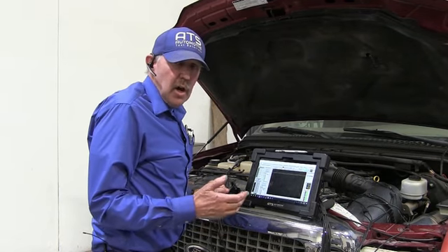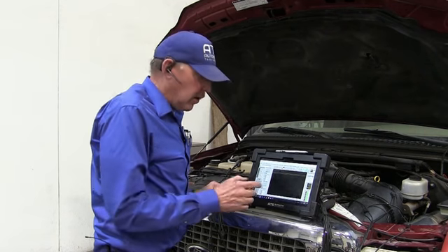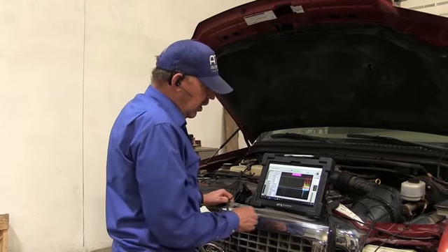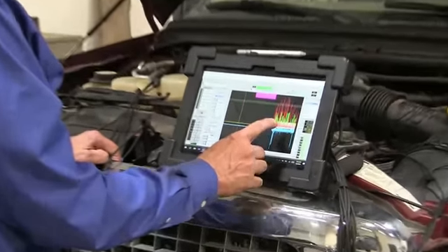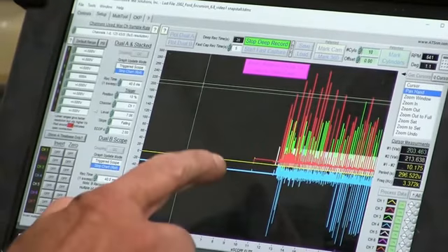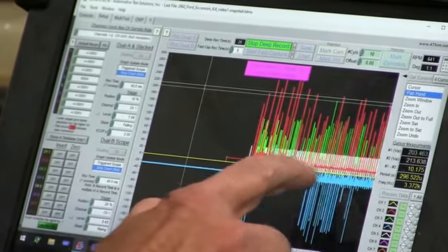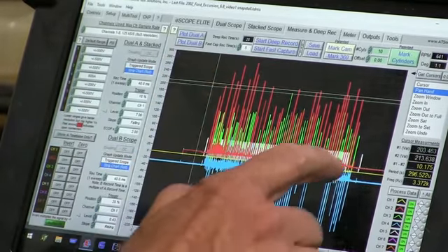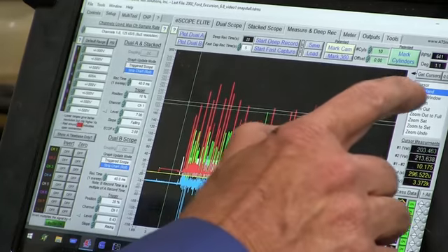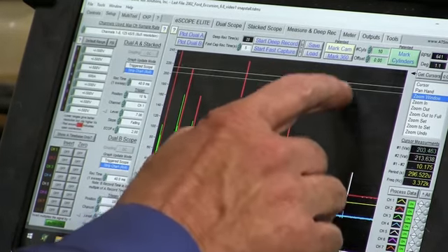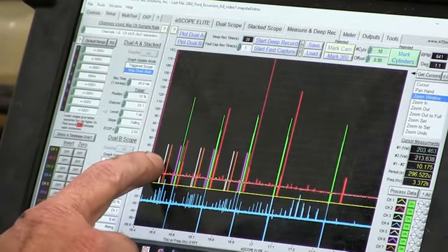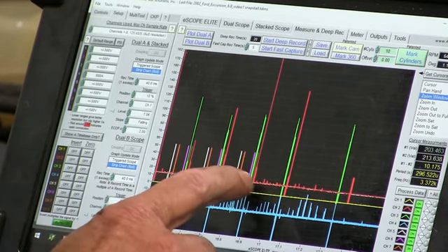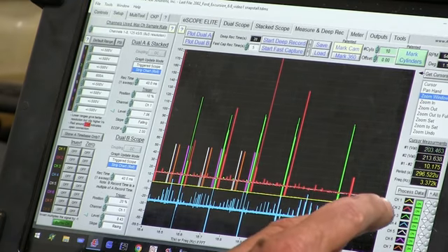Okay guys, so we know that the coil is bad now, so now I got into some of the injectors. Okay guys, so now we're on the injectors and a couple of coils, and we can see that the amp clamp on blue, that's on the negative position of the battery, and we can see that it just died right there, it just stalled. Okay, so let's look at this. See how we have these injectors right here and here and here, and they just stop? And when they just stop, I still had coil strikes, but the engine died because we're not fueling it anymore.